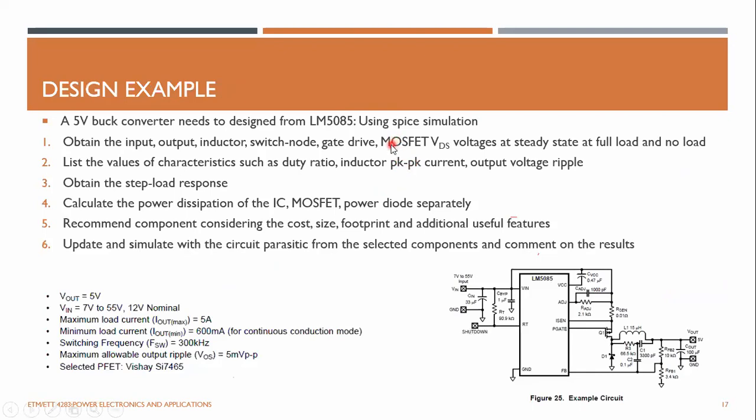Okay, so today we're going to implement, design and simulate a 5-volt buck converter using LM5085 and TINA-TI SPICE simulation. So you have to obtain the input and output voltage waveforms, the inductor voltage, switch node voltage, gate drive voltage, and MOSFET current.